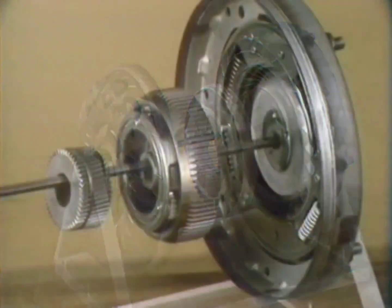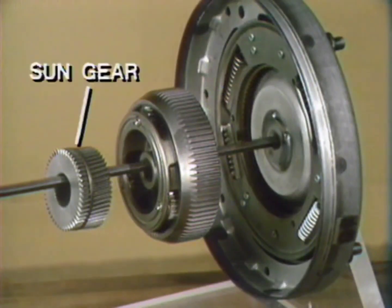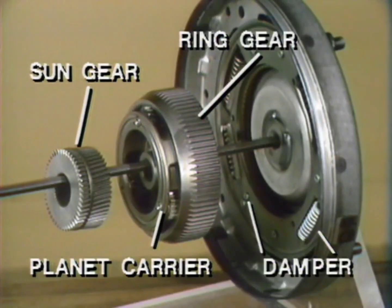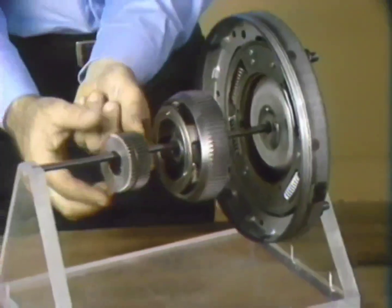The new parts are the splitter planetary unit, composed of a sun gear that splines into the turbine hub, planet carrier assembly that drives the intermediate input shaft, and planetary ring gear that is splined into the damper in the converter cover. The damper, similar to the damper in the automatic overdrive converter, cushions the mechanical input drive.